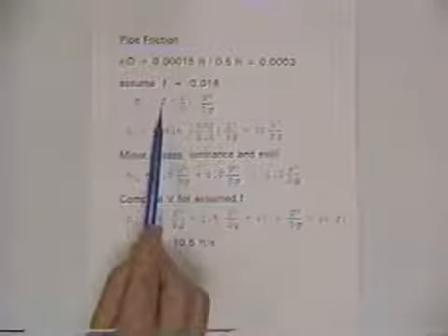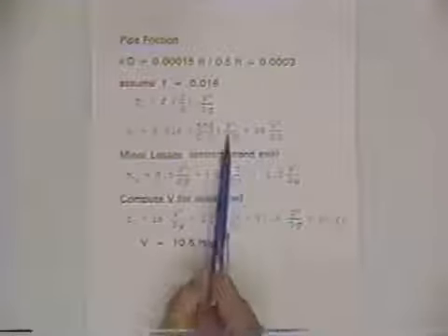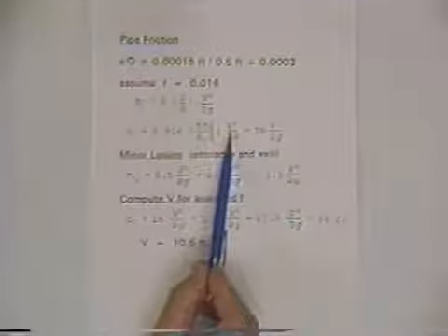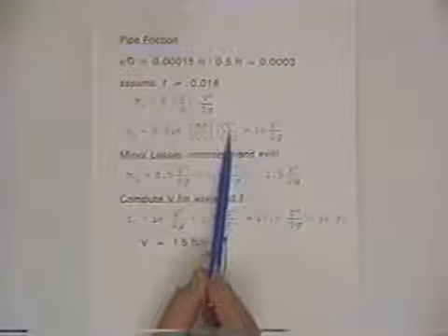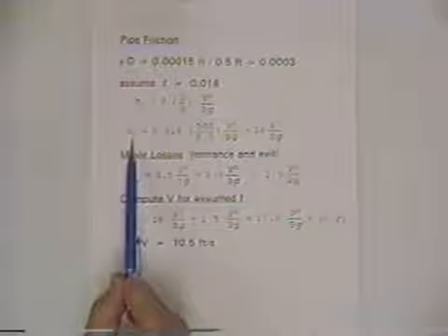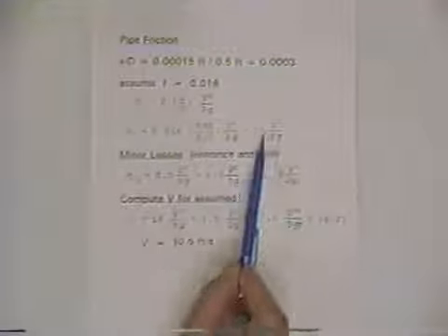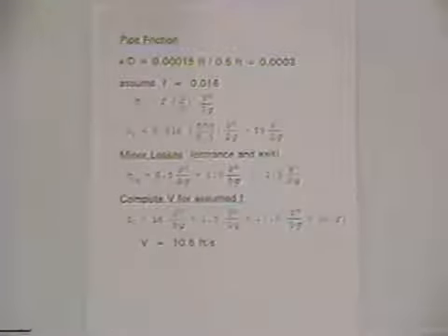And so we plug in the number for the friction factor and the length of the pipe, the diameter of the pipe. We don't know the velocity head, as we've just said, so we just write down the velocity head, and we find that the head loss in that 500-foot long length of pipe is 16 times the velocity head.